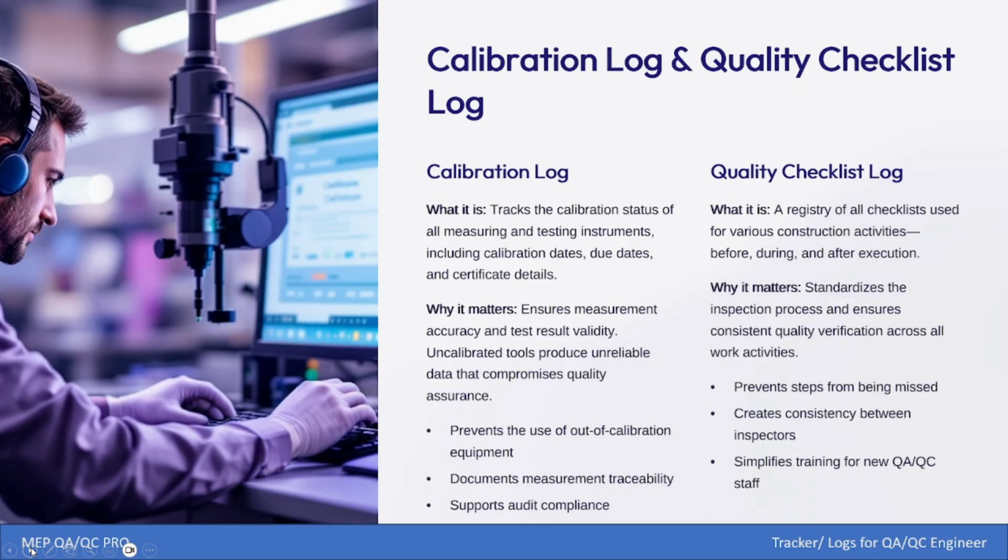QAQC checklist log, where you will register all your checklists for installation, testing, commissioning. You will make your own perfect register showing that you have a perfect checklist for your projects during its execution, testing, commissioning to handover. Everything you have, so that you can prove easily, or you can track easily, all the installation which has been performed at site.